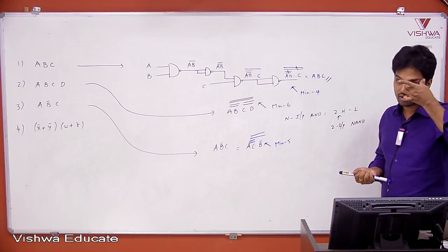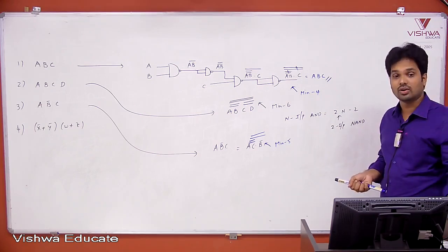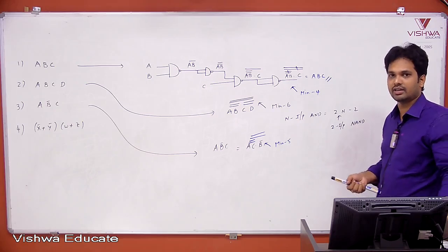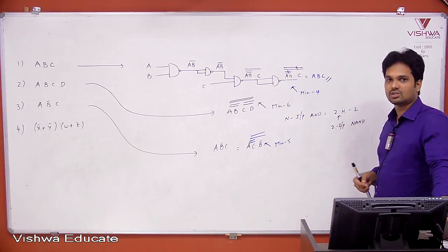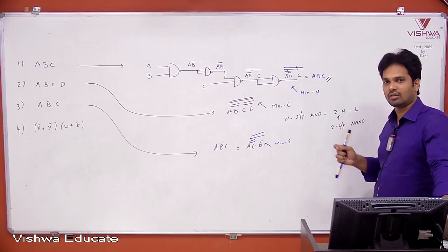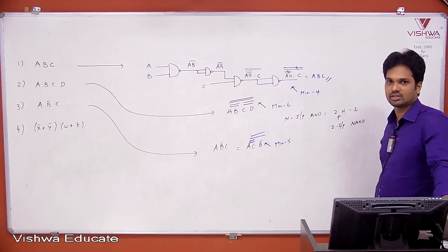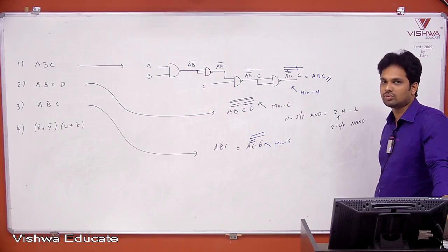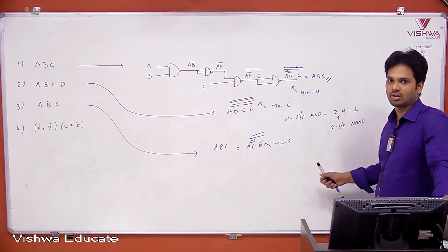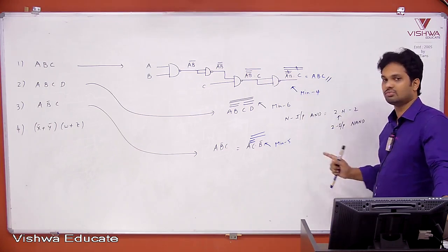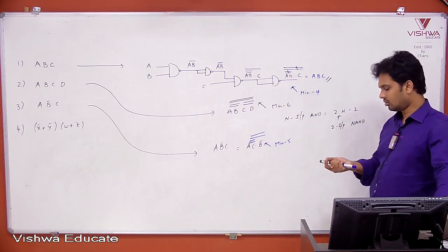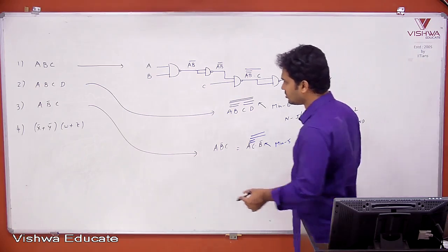For XOR and XNOR, I have already given you the shortcut answer for implementation with NAND gates. If the product is given like this, there is another case which we call the AND OR function. Next I will discuss it in 2-level logic. We can also use that concept later. For continuity, if it is a product form, you can always use this one. Now, let us use this one.